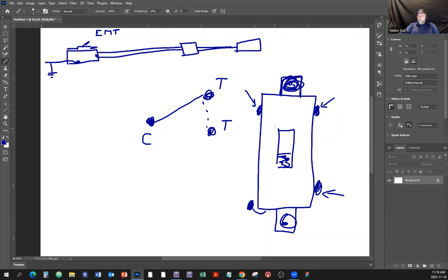In Canada, from what I know of the electrical code in the States, even though it's metallic tubing, you still have to run a separate wire inside and connect it to all the bonding terminals. Now, those things might change with time, who knows, but at this point, 2022, that's the way it is right now. That's only if it's EMT.